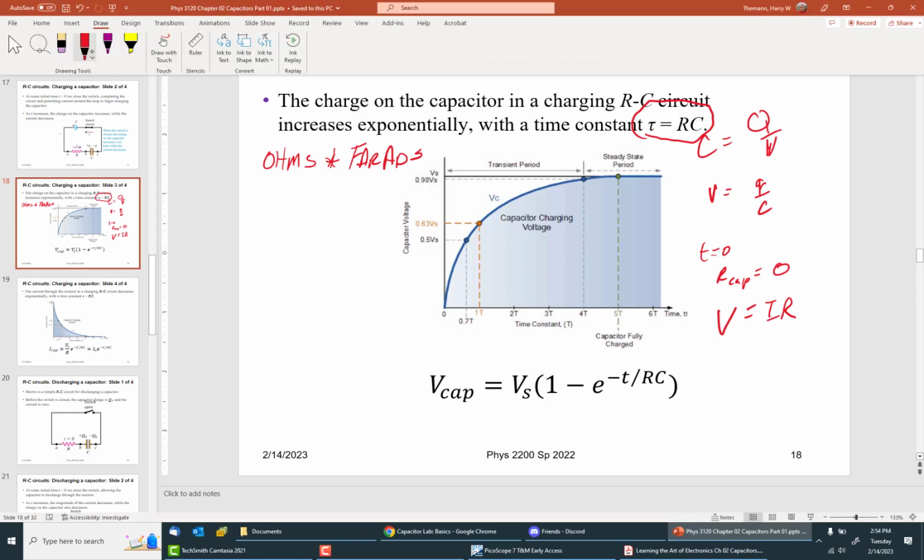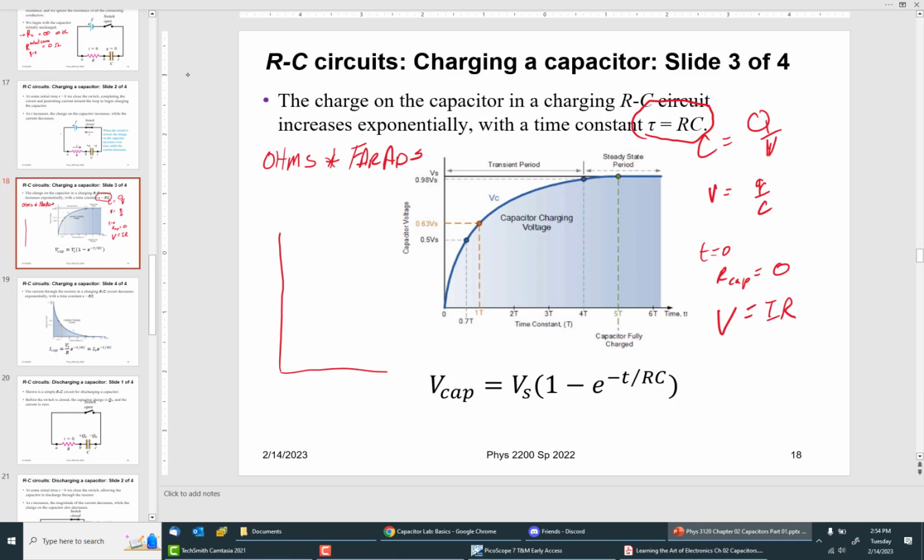I just have this graph. So what you do on your oscilloscope is you set it up so the graph you see starts and plateaus on two lines. You can imagine if you're clicking it, it's never going to work, right? So you use the variable voltage. And then you know the delta V here, and you just figure out where is 63% of that, and then you slide this back and forth and pick up a convenient line. I'll show you. Just giving you a hint right now.